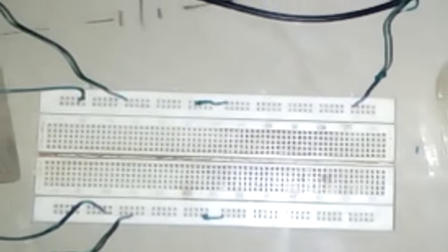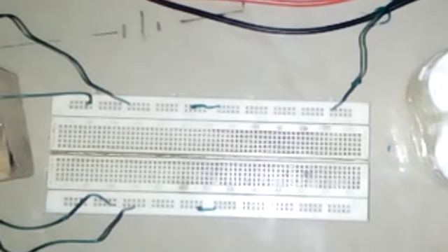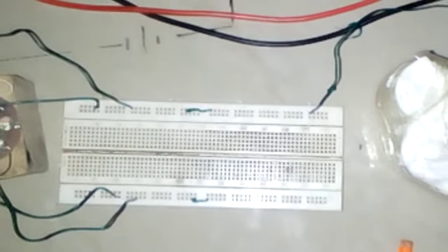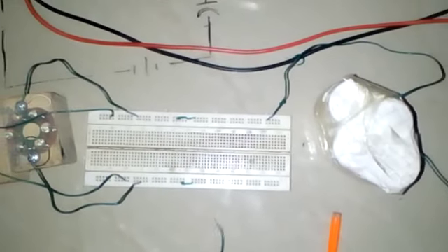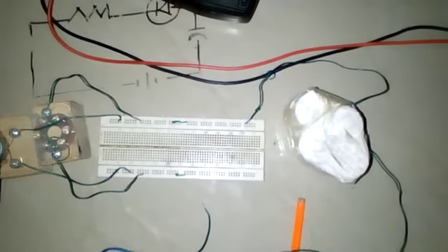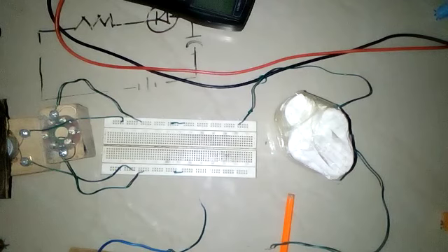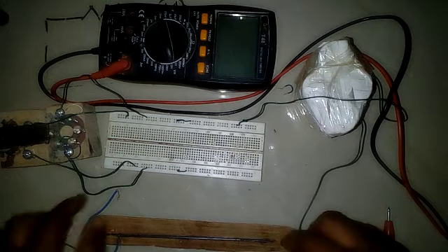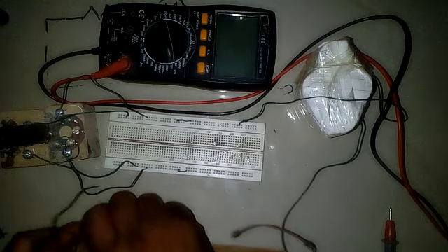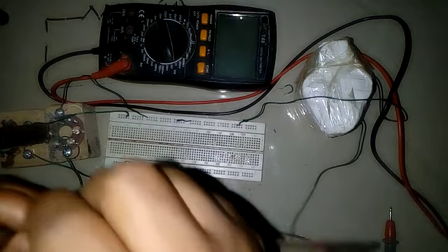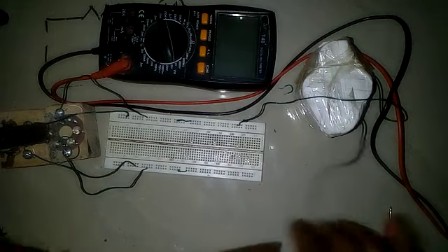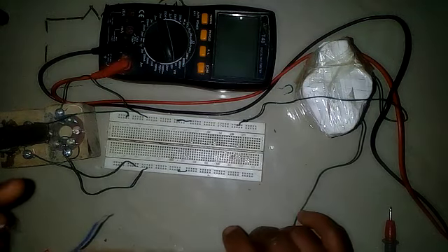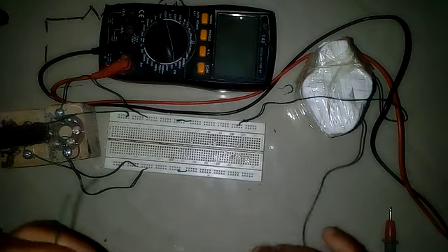We want to be able to vary the speed of the motor and the brightness of the LED. So I have my homemade resistor here. I'm going to insert it in series with the circuit. This is one of the terminals. This one cannot, if you look at it, this is a soft wire. It will not fit into the holes in the LED board. So let me attach a jumper cable before I insert it in.